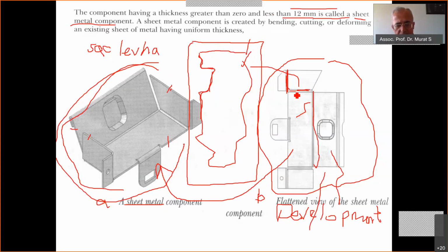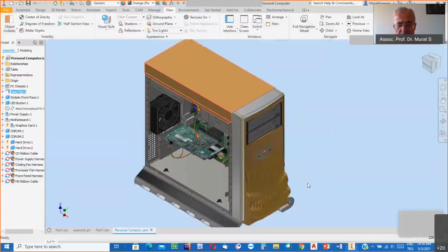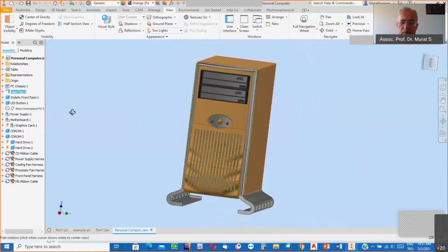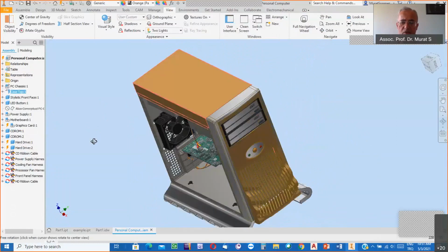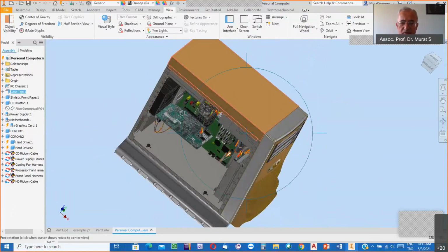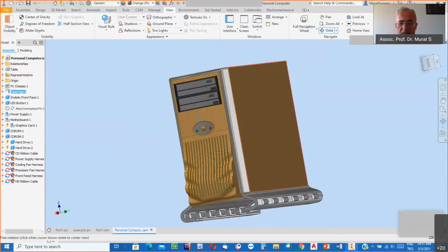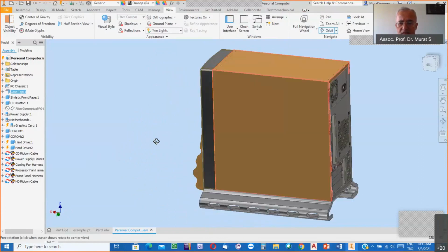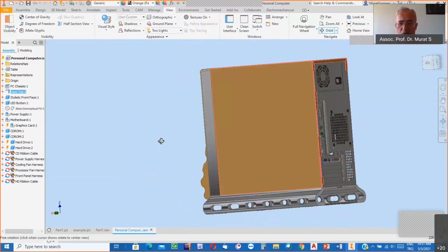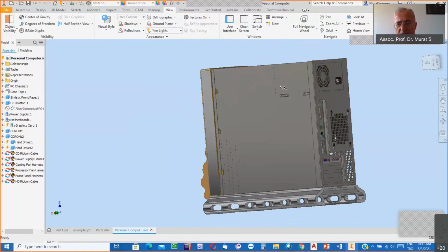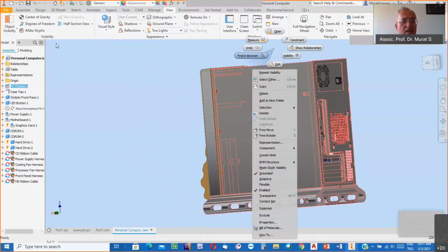After delivering such sentences, well, open a parenthesis and then see some examples. For instance, here, this is no doubt an assembly, the model of an assembly, the main part of a desktop computer. The cover of the desktop computer has been disassembled here to allow us to see the inside of this box. If you see the object in this direction, yes, it is like a black box, but thanks to removing this cover, yes, left click, indicate and deselect the visibility, and then the rest can see the inside.